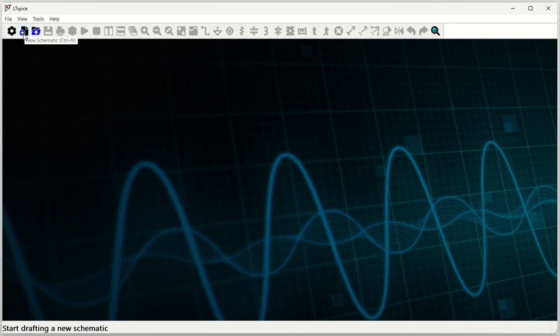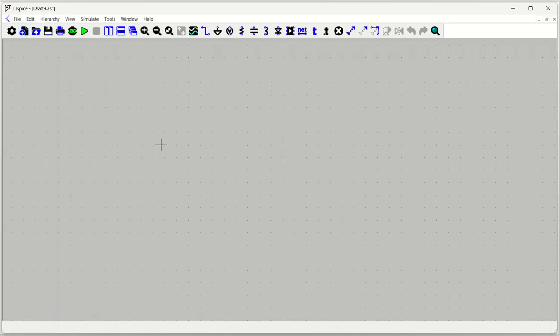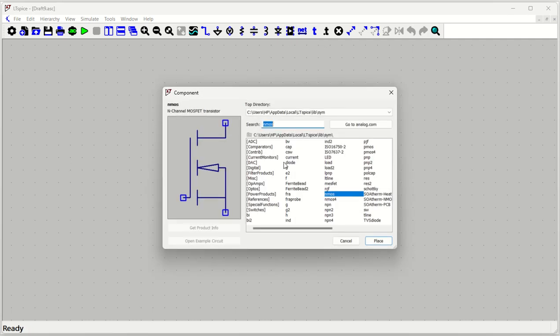Anyway, let's open LTSpice, and what we can do is we can quickly open a new window, schematic new window. Okay, now what we have to do is we need one opamp to put in, so that we can run this particular simulation, and we are going to see inverting amplifier with a gain 1, 2 like that. We'll try to vary and we'll simulate the functionalities. So go to this part and put opamp.